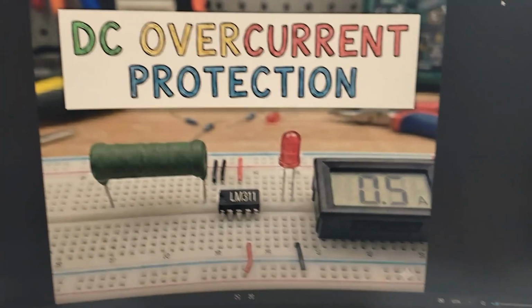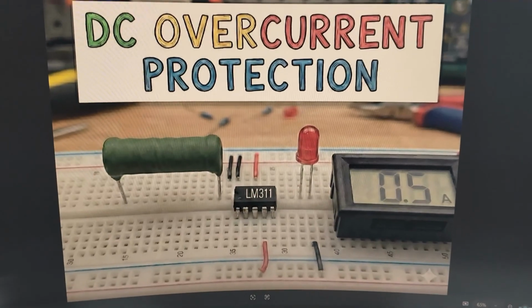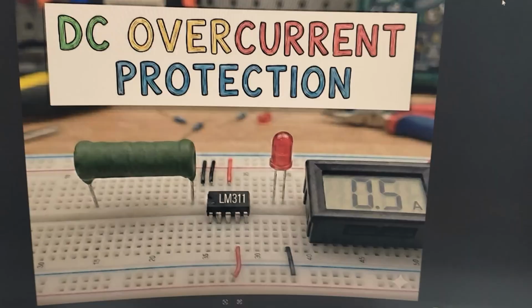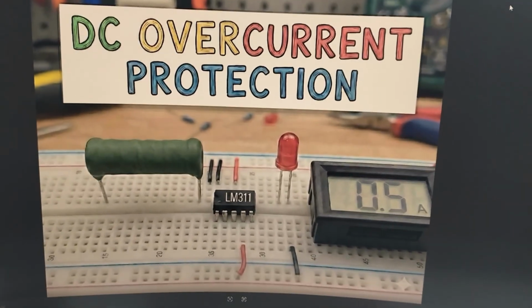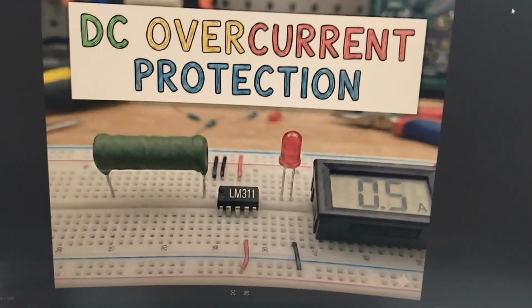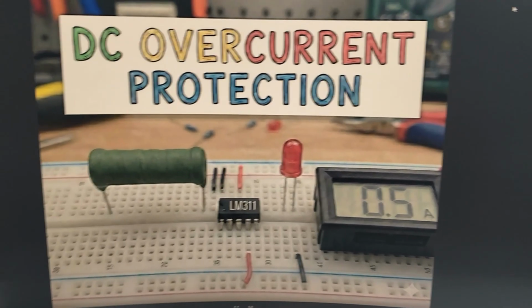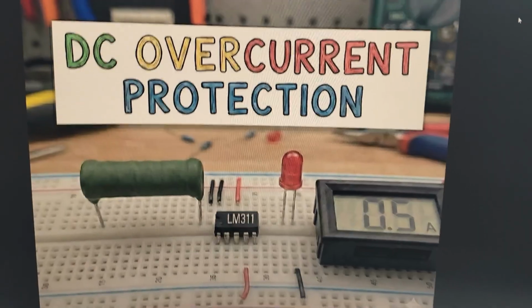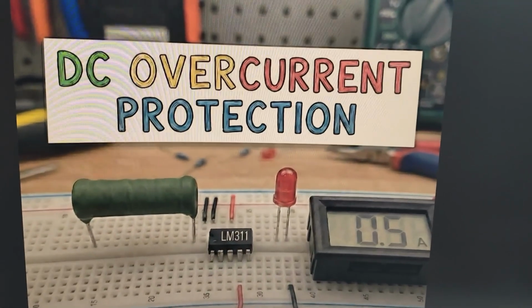And it has to do it fast, because all these devices, especially MOSFETs and solid state switches, can't even tolerate overcurrent for a few microseconds, so it has to be within that. Generally, if it's a microcontroller based solution, they use Hall effect sensors, sense the current, sample it, and then maybe stop the PWM. But today we're going to be implementing it in the discrete way, the analog way. So let's go into the circuit.